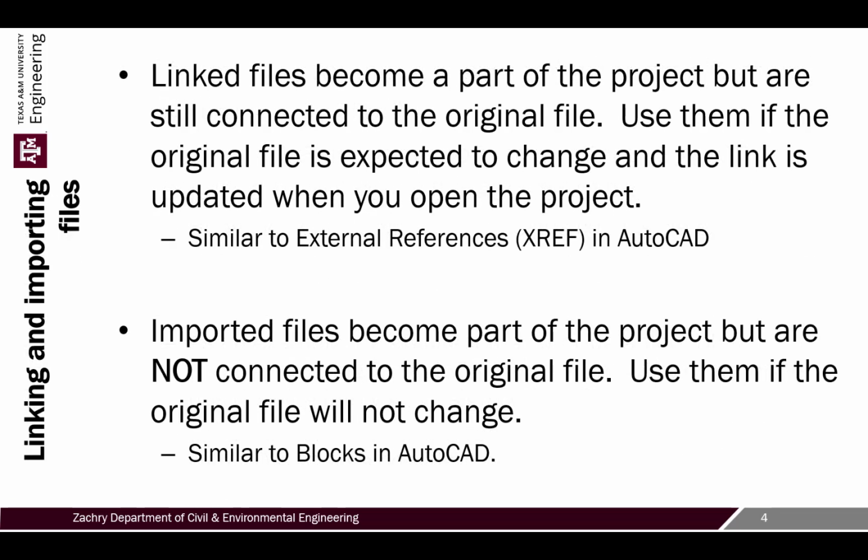A couple things to understand about the different ways you can bring a file in, and this is going to be important for class this week because we're going to break it down from another approach, is the idea of linked files and imported files. Linked files become part of the project, but they're still connected to the original file. So if you have one architectural file being worked, and a structural file for the structural group, and an MEP file, they can be driven from that one original file.